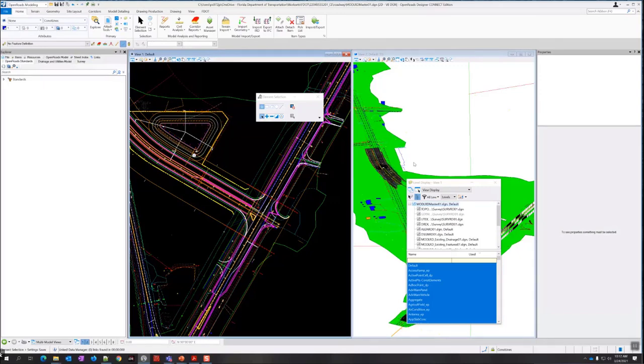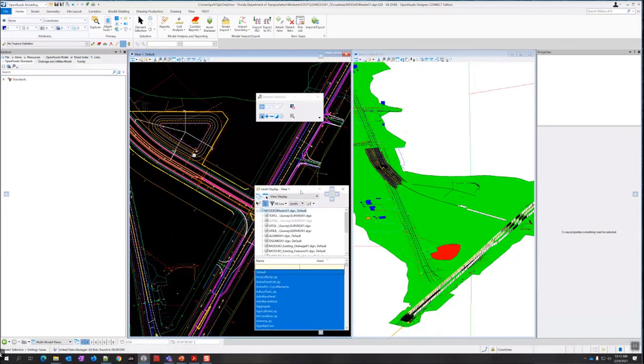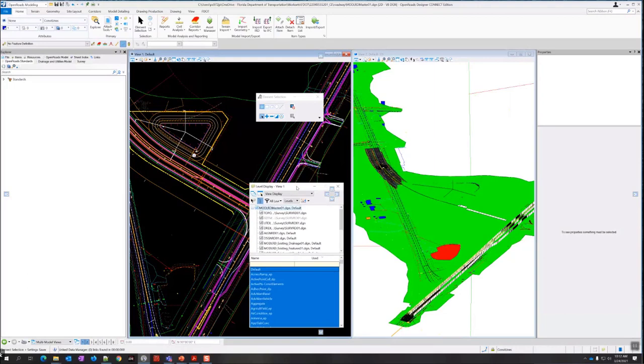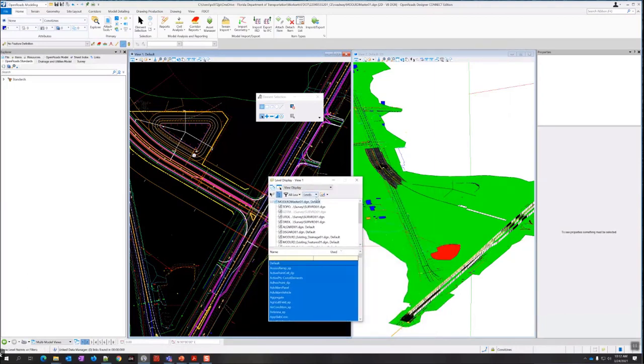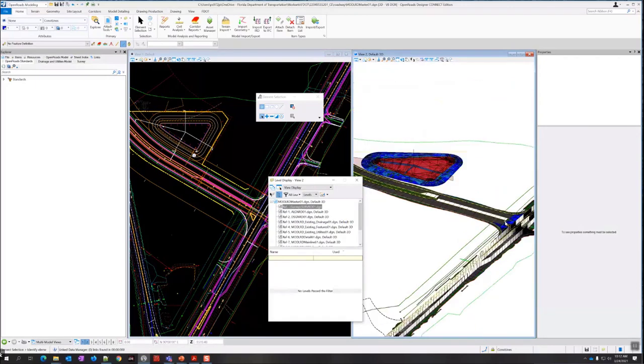Since we have this created, the first thing I'm going to do is export the iModel. And so whatever I think is attached here is going to be exported as part of the iModel. So let's just make sure that you have everything attached that you need and anything extra that is not attached. I'm just going to check in my 3D view quick. If I turn off the server RD, turn off that display, just make sure my proposed model all looks right. And it does. I'm going to turn off constructions here.